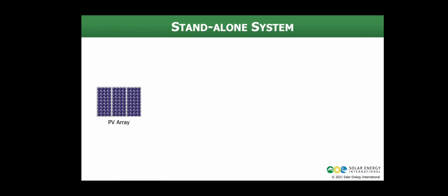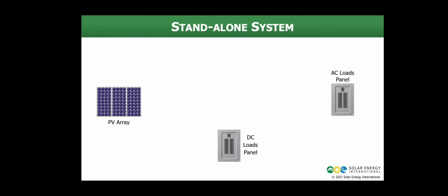Any PV system that functions independently and is not connected to a larger utility grid is called a standalone system. PV direct systems, which consist only of PV modules and the load they are powering, are one form of standalone system. In addition to the PV modules, a standalone system can power DC and/or AC loads, depending on the application. There will also be some type of storage, likely a battery, which will be used to store energy that is generated during the day for use during the night.